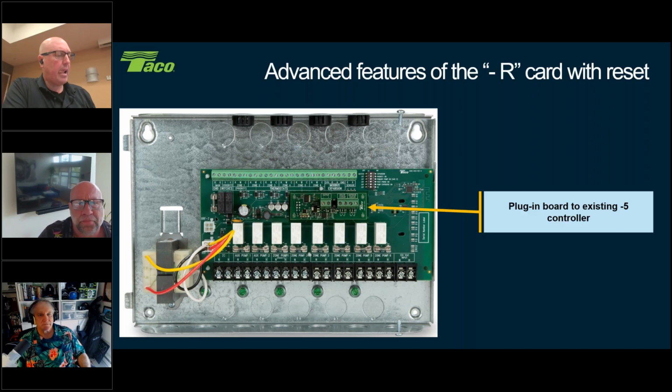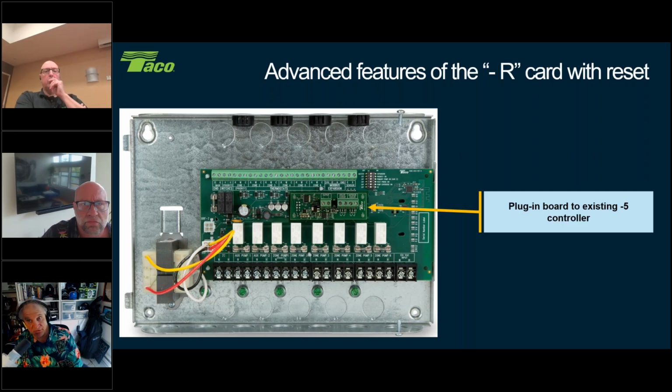I'm not sure. And there's also a question about can you calculate system flow from the boiler delta P or delta T? If you know the BTU load and you have the delta T readings, in theory you can calculate system flow. It's just a refiguration of GPM equals BTUH divided by delta T times 500. So you fill in what you know, you should be able to figure out system flow as best you can. You need a good way to figure out what the BTU load is at any given point in time. That's the hard part, because that changes with the weather, right?